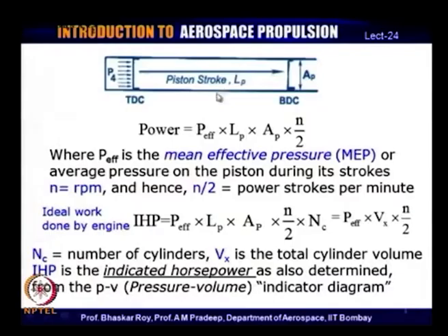The pressure gets a little restricted because if you have a very high pressure, the piston would have to be built with very heavy material. That is what is normally done, for example, in a diesel engine, which is made of very thick material to withstand the very high pressure that is normally created in a diesel engine.